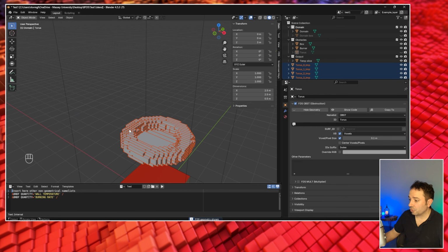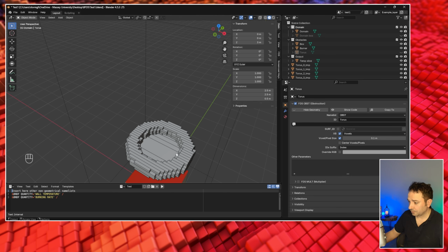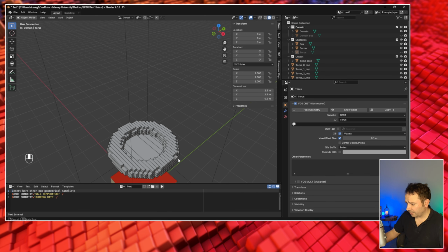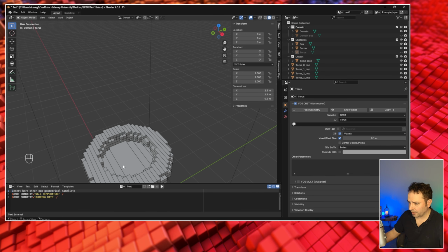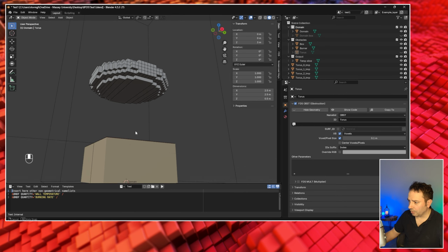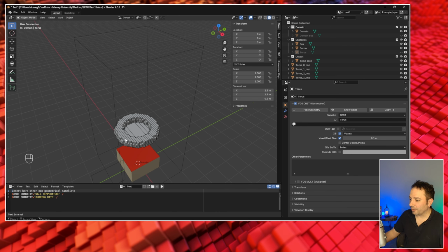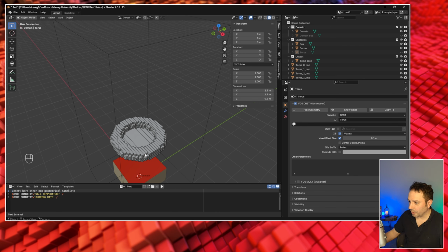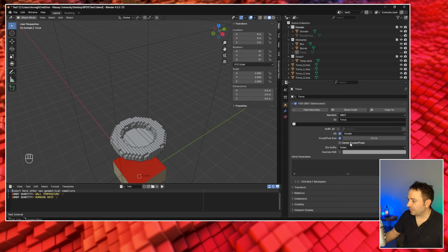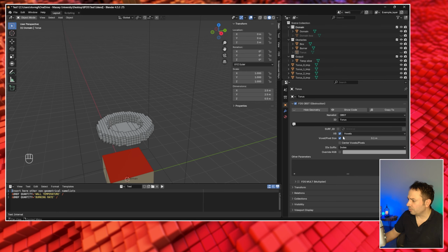And if we go and see the geometry, you'll see that this mesh has been decomposed into many different elements. You can see that there is also something that is not really what we wanted. You can see here that we have a hole, the voxelation, let's call it voxelation, didn't work really well. Probably this is a bug that we need to fix in a future version of BlenderFDS. And as I said, I'm not really happy with this solution. So